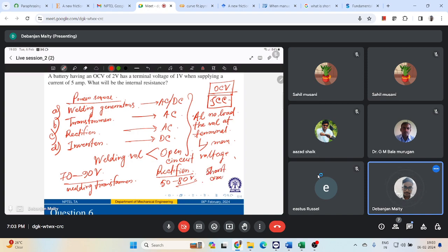As I was saying, initially you have to contact the electrode with the workpiece, and then you retract the electrode from the workpiece surface. Whenever you create that contact, it generates short circuit current, and then it breaks that metallic bridge to increase the current density, so that the arc generates there.